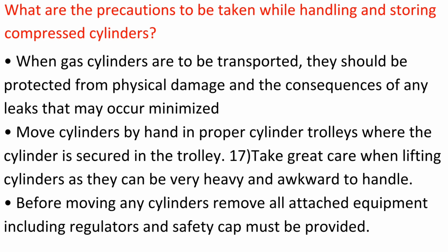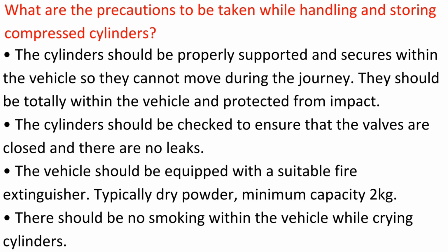Move cylinders by hand in proper cylinder trolleys where the cylinder is secured in the trolley. Take great care when lifting cylinders as they can be very heavy and awkward to handle. Before moving any cylinders, remove all attached equipment, including regulators, and a safety cap must be provided. The cylinders should be properly supported and secured within the vehicle so they cannot move during the journey. They should be totally within the vehicle and protected from impact.